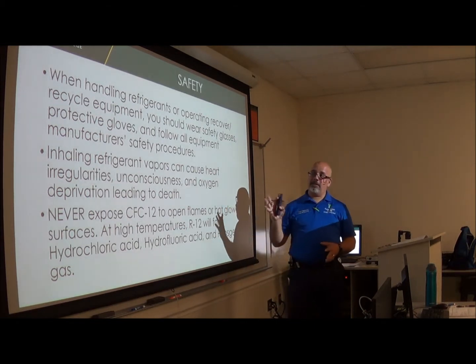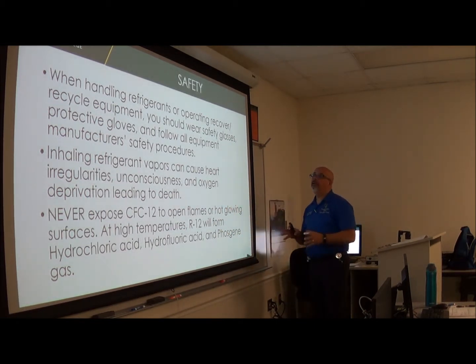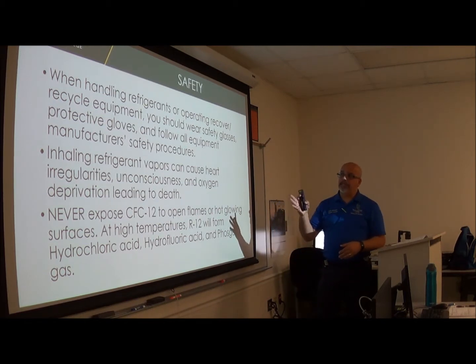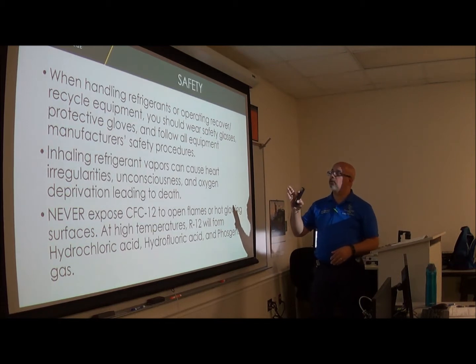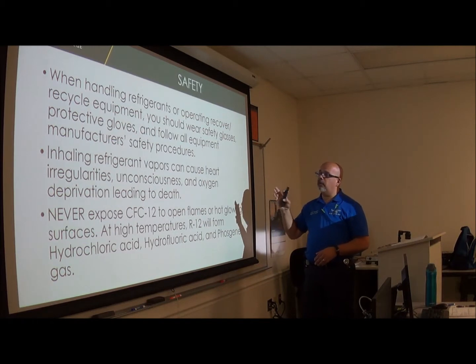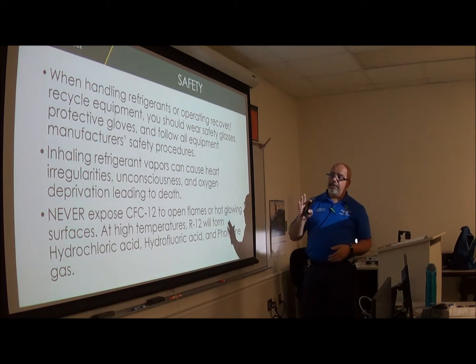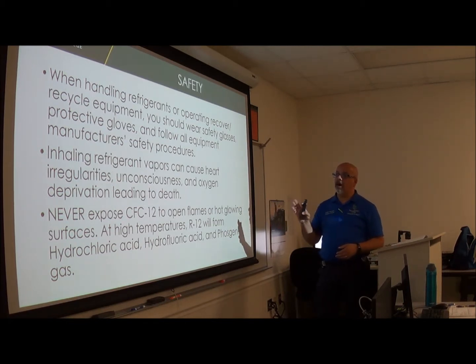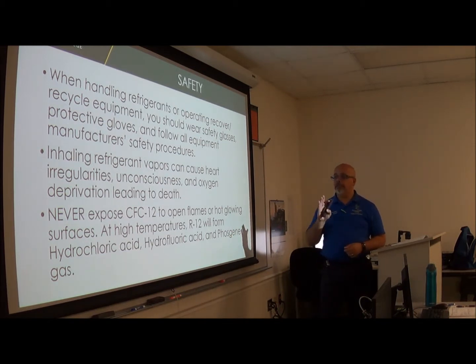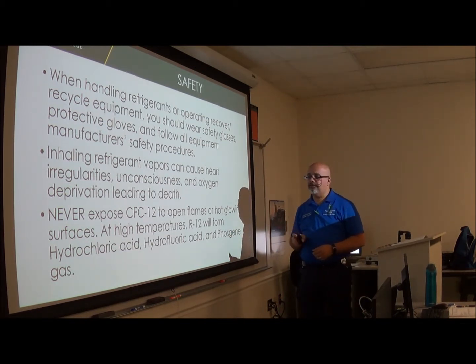Safety. There's three major safety notes that EPA is saying for 609. It says that when handling refrigerants or operating recovery recycle equipment, you should wear safety glasses, protective gloves, and follow all equipment manufacturer safety procedures, just the PPE. Inhaling refrigerant vapors can cause heart irregularities, unconsciousness, and oxygen deprivation, leading to death.